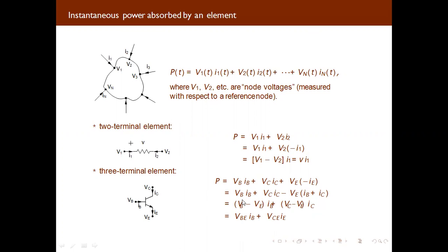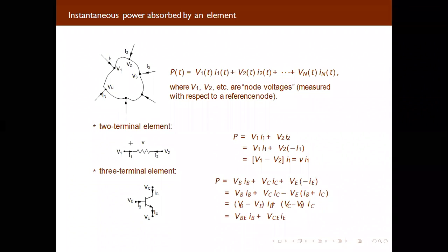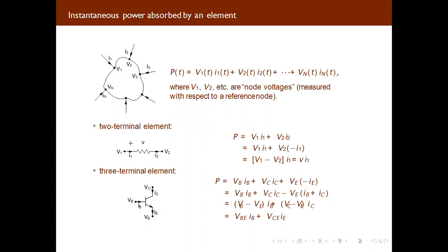I am showing you how we get these equations because in electronic circuits you are supposed to solve for the hybrid model, in our first and second unit, MOSFET analysis. We have seen there that we use the single stage amplifier and all these things. At that time you will be required to know how to apply KVL. That's why I am showing you how you can write this equation. You will need it for MOSFET; I am showing it here for the BJT. So if you are calculating the power here, you will get VBE into IB plus VCE IC.